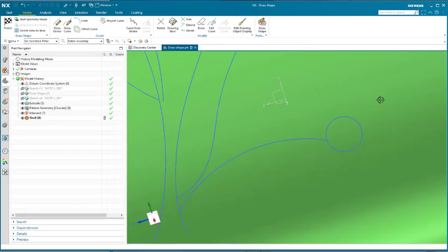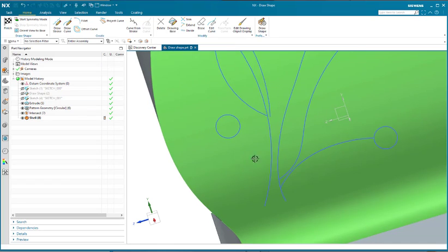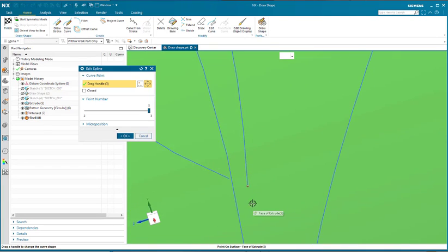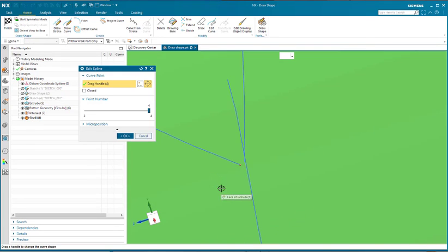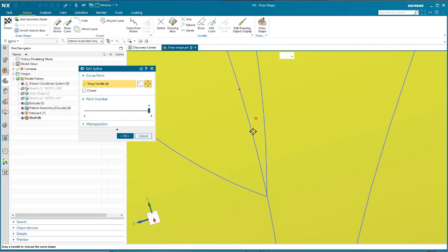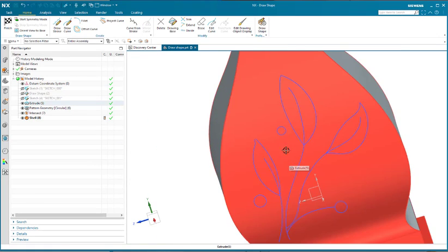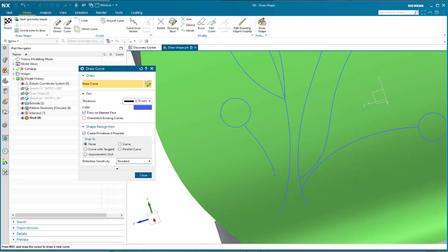Let's clean it up a little bit. Let's make the stem of that berry so it's kind of perpendicular. Let's make that leaf come to a nice point. We don't want any of the entities having a hole in them when you make a full loop. We're going to be extruding this, that's why. So we're just cleaning everything up, maybe add a little bit more geometry.